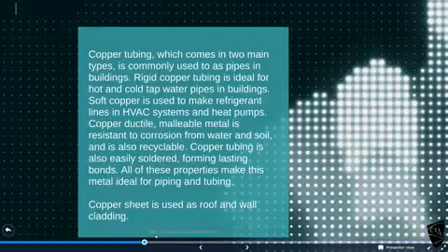It's quite ductile, you can bend it nicely, you can shape it. If you've got sheets of it, you can shape it because it can be used for roofs and things like this. It is resistant to corrosion. It's very recyclable, and it's got quite a high value to it as well. It's easy to solder and join. A good tradesman will be able to do a lovely joint with it instead of relying on compression joints. They all make it ideal for plumbing, basically.